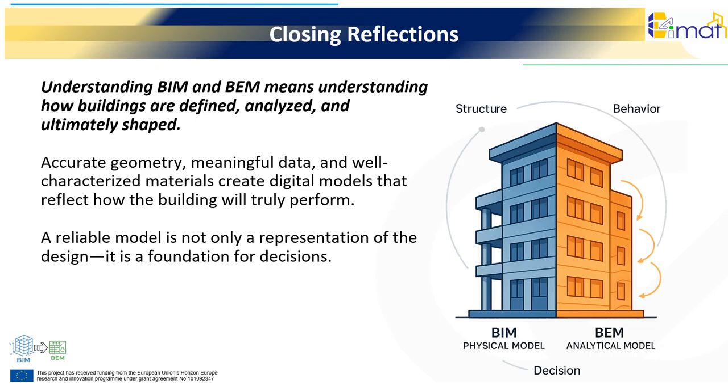BEM, on the other hand, focuses on the analytical behavior of that structure, evaluating how heat moves, how spaces respond to climate, and how much energy is required to keep occupants comfortable. Throughout this process, materials play a central role. The quality of the information we assign to them determines the reliability of the entire digital workflow. When materials include accurate physical and thermal data, supported by testing, documentation, or verified specifications, the building models we produce become much more than illustrations.